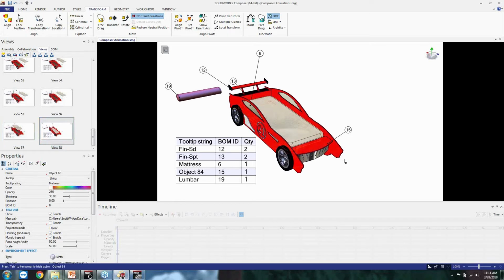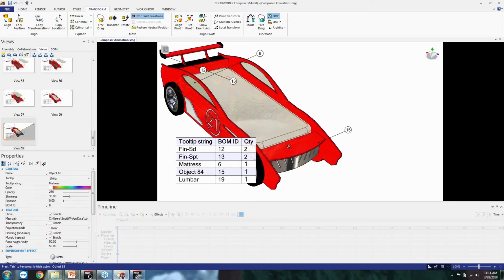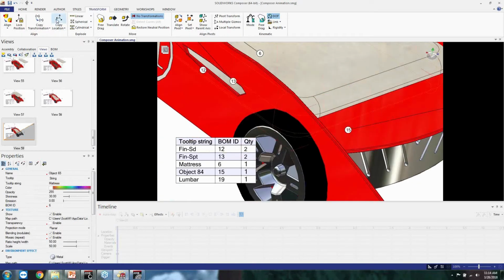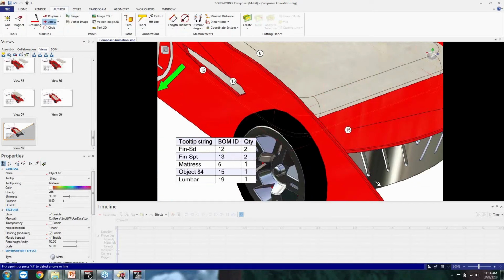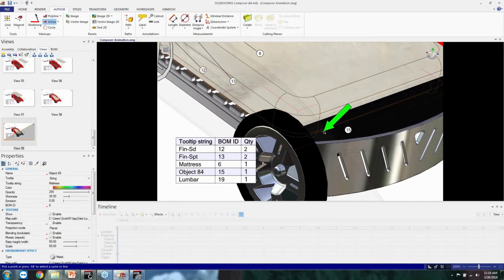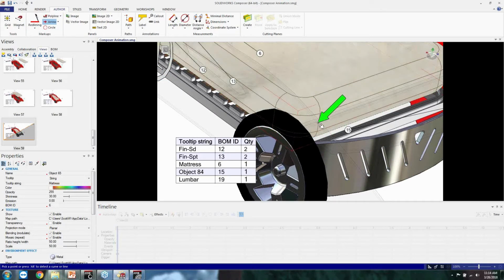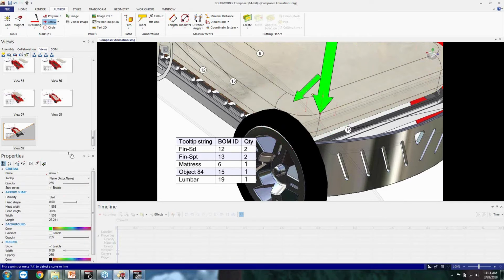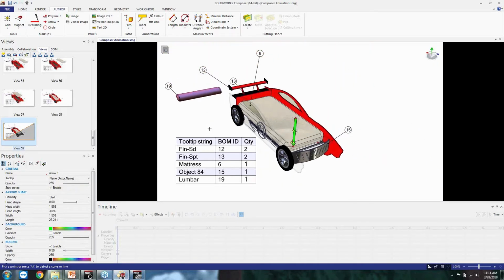Now if I wanted to, I could put an arrow. So hey, even though it's obvious what's happening, let's put an arrow in there to show the arrow going down. So for that, I'm going to zoom in. I want to create a camera key so I can get back to this angle that I have. We'll zoom in, author, arrow, hit tab just so I can see. I want a vertical edge like that guy right there. Select that vertical edge, click it, get our arrow, double click the camera view to get it back.